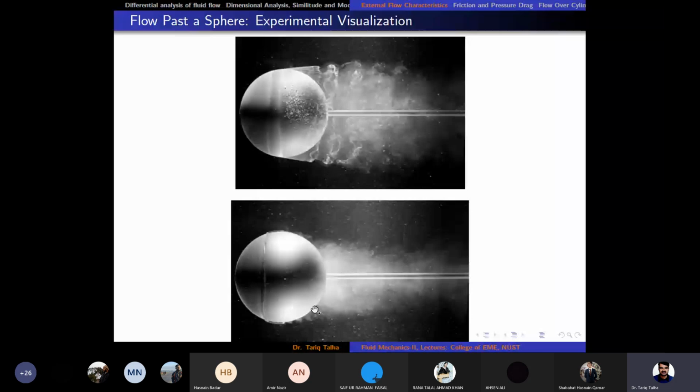So on one side we have got a vacuum due to flow separation, on the other side we have got flow attachment due to the turbulent boundary layer. So if the upper side is shiny and the lower side is rough, the ball would always travel towards the shiny side, because the shiny side has got flow separation and the rough side has got the boundary layer attached due to turbulence. So that is the case of reverse swing in a cricket ball.